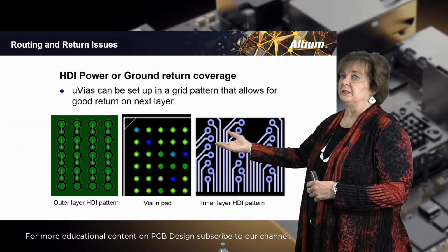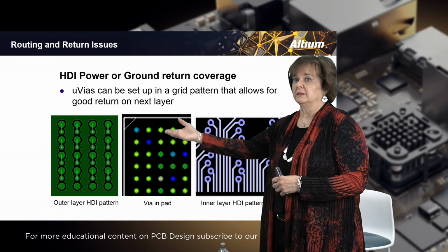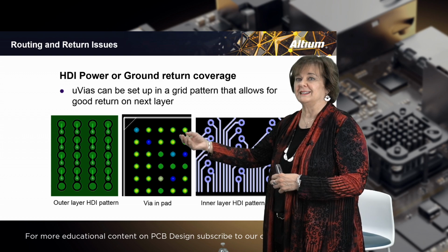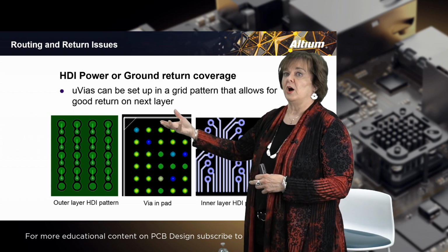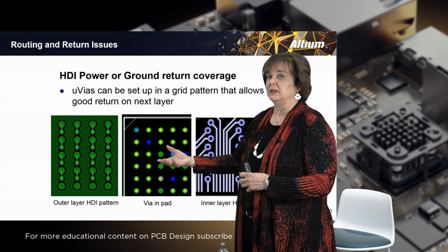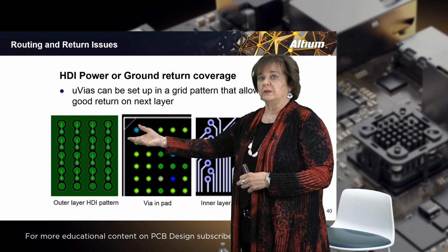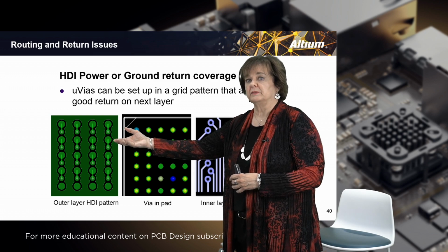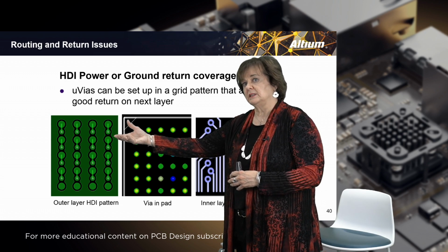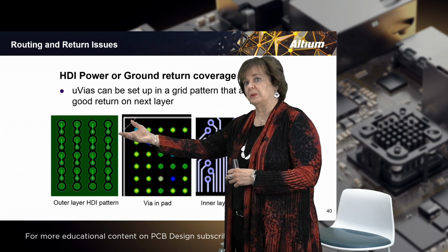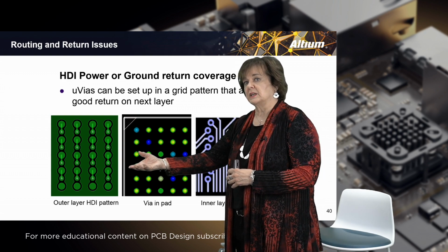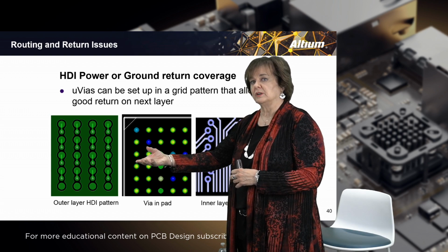For example, via-in-pad has very good plane possibilities because the via is in the pad itself. There are very small anti-pad openings, and all of this black area could then be grounded. Or there's a way of setting up the HDI here, such that there's lots of green area, which is the ground plane, and lots of signals can return against that green area without causing problems.